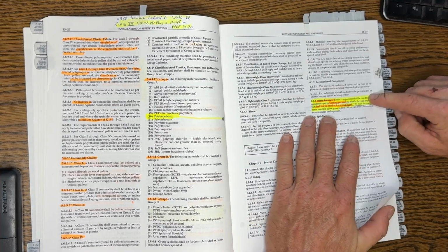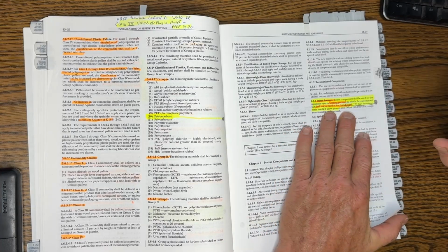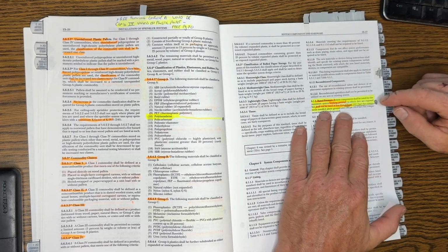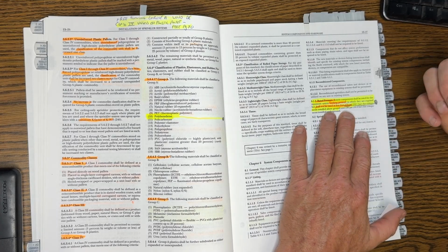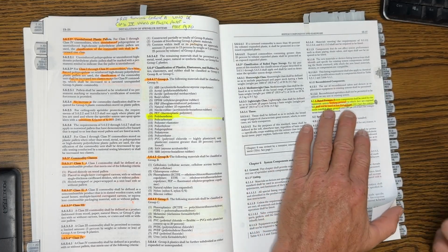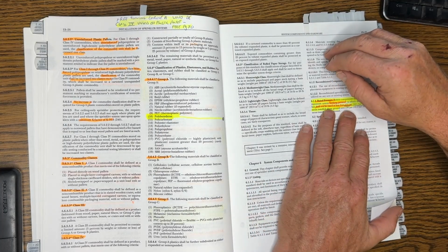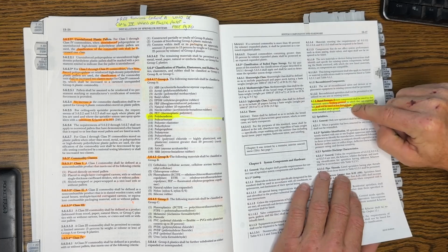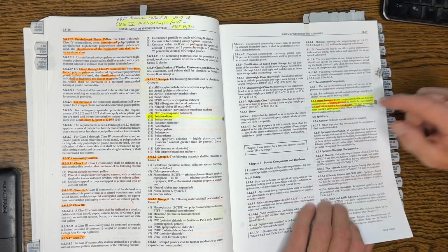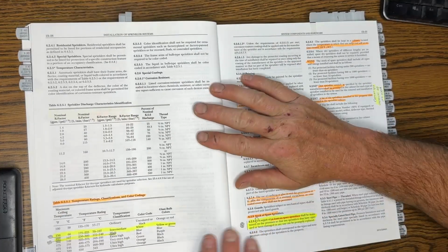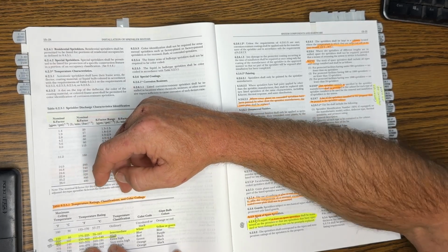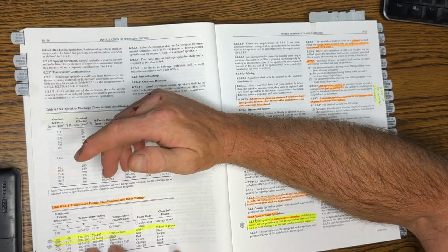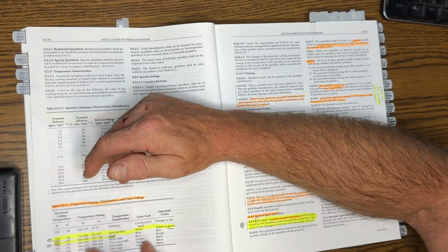Technically, you have to design the sprinkler head at the manufacturer so it can handle 175 psi. But the minimum flow that a head can have is 7 psi. You're going to be tempted to put 7 psi. They're going to try to trick you. The answer is 175 psi. That's what the maximum it's designed to. So it's important to know that. Temperature rating, classification, and color codings. So just know that an intermediate is 150 degrees.